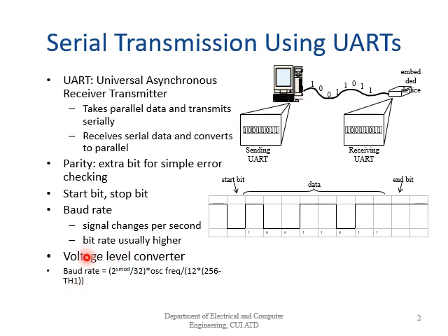We can also use UART for voltage conversion, like we can say this is high and this is low, so kind of converting voltages. Finally, we can also use a general purpose processor to implement UART in software. So we can make UART using software rather than hardware. So that was about the UARTs. You need to remember what is baud rate, what is bit rate, how we can calculate baud rate, and what is parity. Let's move on to the next slide.